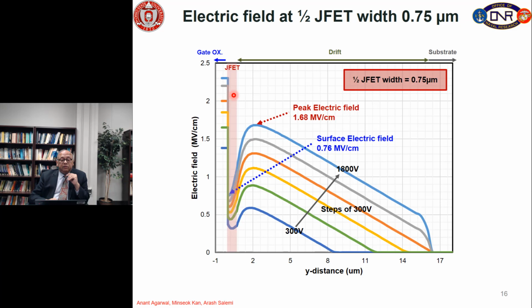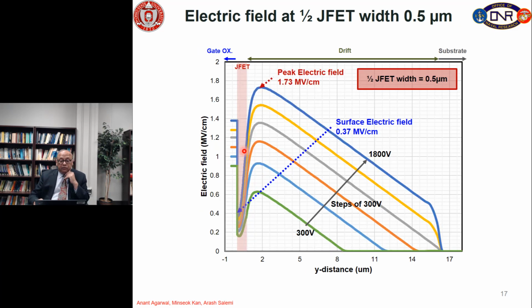So this is a very safe design, but you can see as we are bringing the JFET region smaller and smaller, the resistance of that JFET region will go up, as you just saw in those calculations. So we have to be mindful of that.